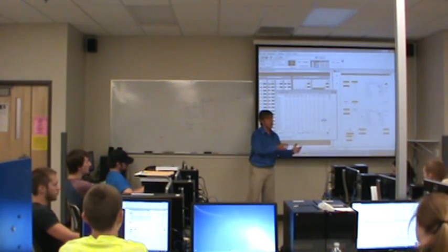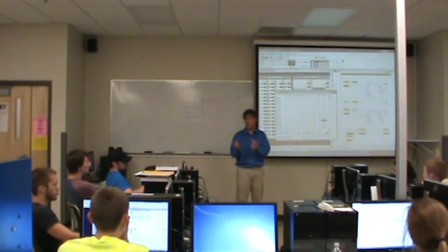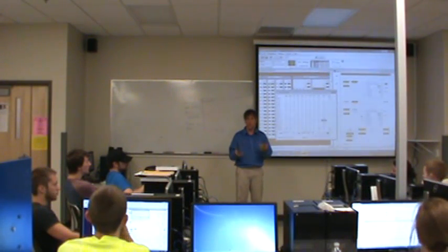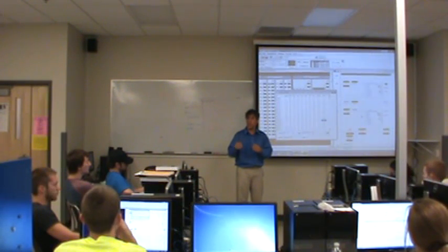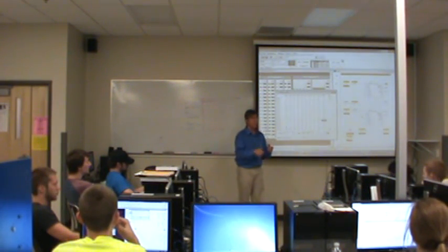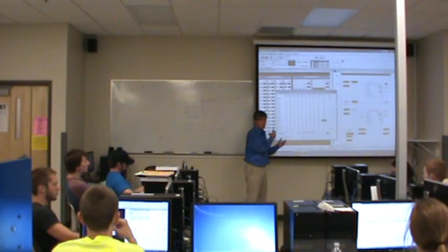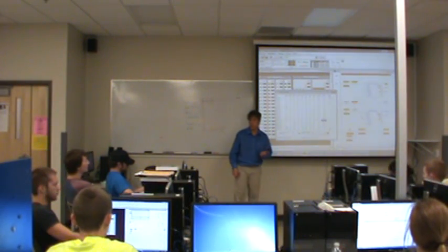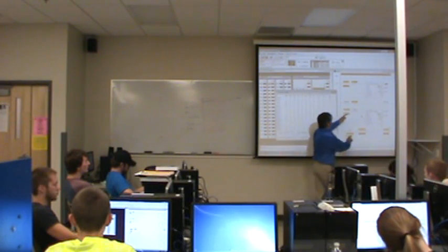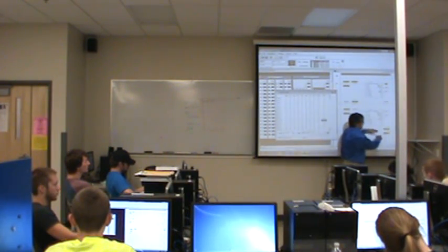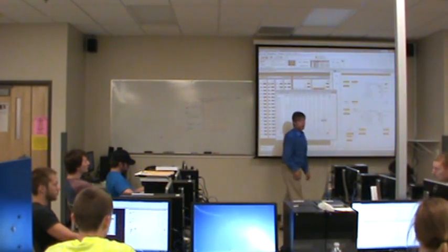Silo simulator goes along. For some reason, the box comes underneath the hopper. We overfill the box, or the box falls apart or something. We got an emergency, hit the stop button. In that case, you need a reset button so that the sequence would start back over at the beginning of getting a fresh box to fill. Does that make sense? And so you need a way of resetting both the sequence compare and the sequence output, and it's very common to have a reset button for that purpose. Okay?